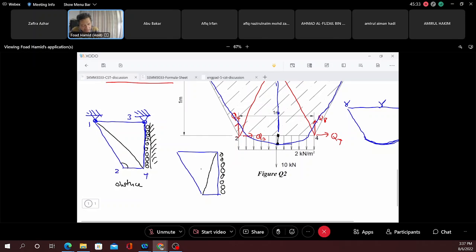Okay, which means it is just a mathematical thing saying that the angle is more than 90 degrees. Okay, that's it. There's one angle which is more than 90 degrees. In certain finite element software, because of the formulation, when you have an obtuse angle in your element, the result will not be as accurate as you want. So avoid anything that is more than 90 degrees.